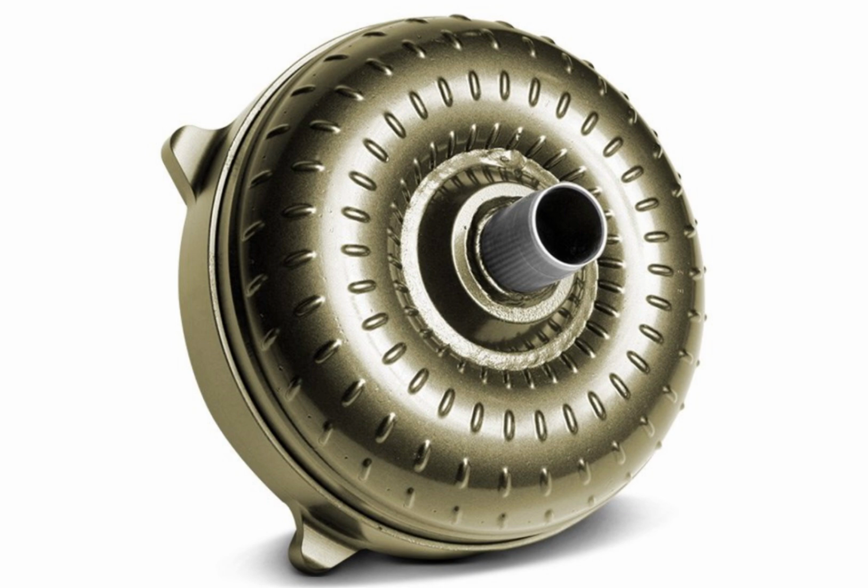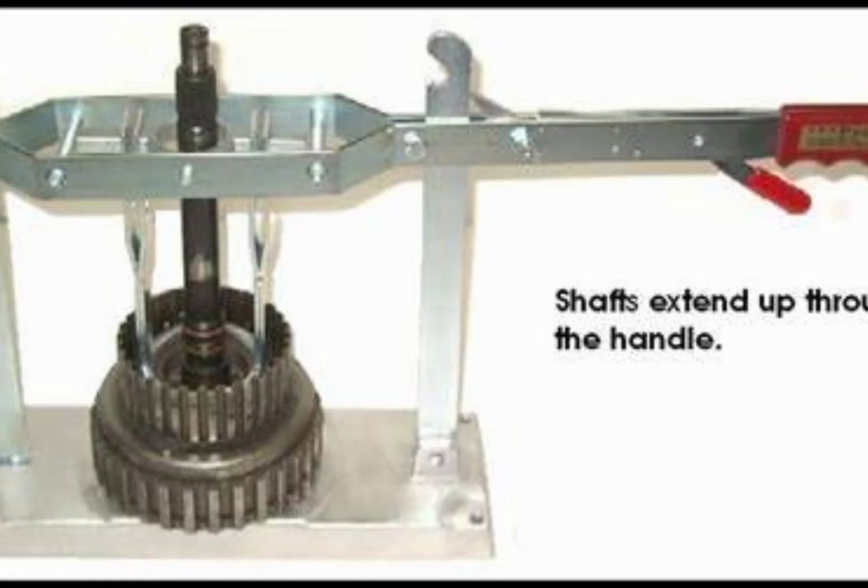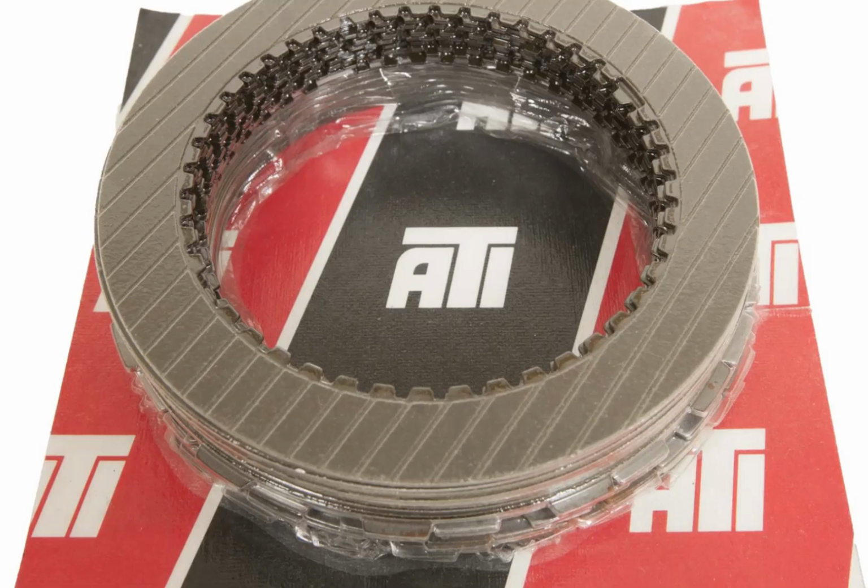Step 3. Repairing and replacing parts. Clutch replacement. Use a clutch spring compressor to remove and replace the worn clutches. Install new friction discs and steel plates in the correct facing. Ensure proper stacking order as per the service manual.